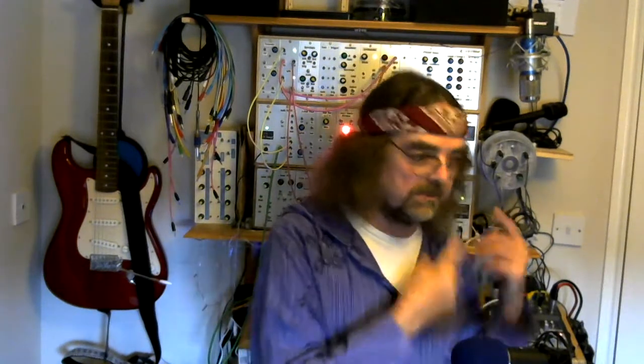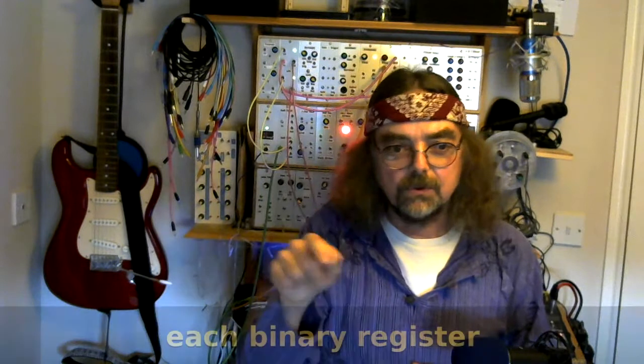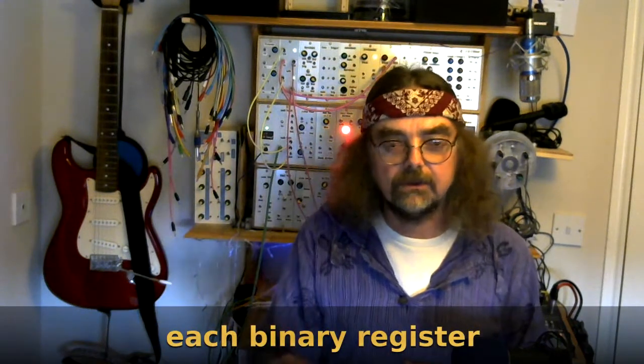Now the thing that makes that useful for synth use and music use is that if we step through the binary registers that are counting, and put a clock signal in, each count would be a half of the clock signal. So you get a half, quarter, eighth, 16th. If you put an audio frequency in as your clock signal, you will halve the audio frequency. If you halve an audio frequency, you drop the frequency down 1 octave.